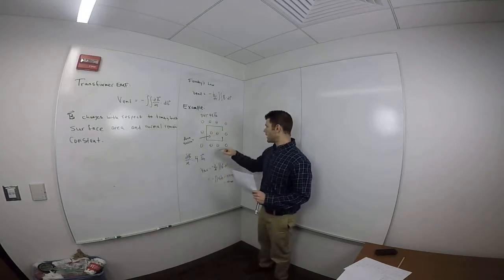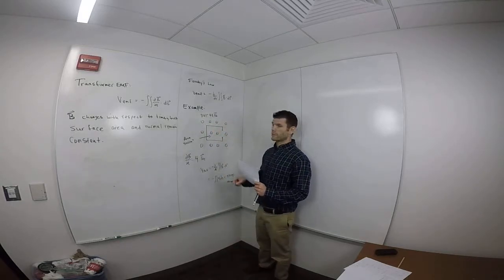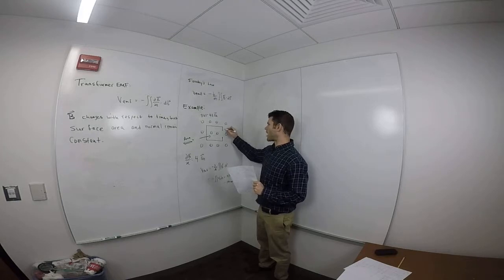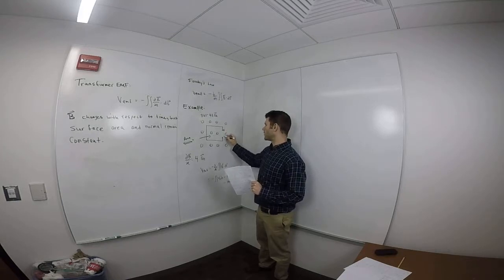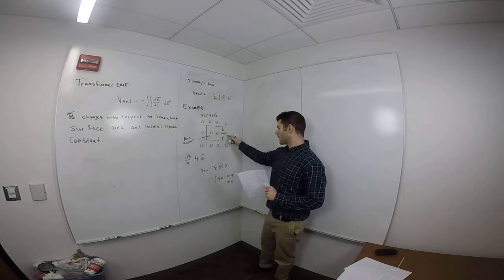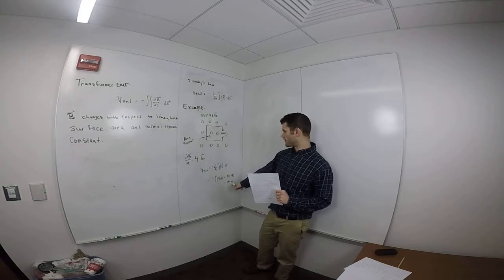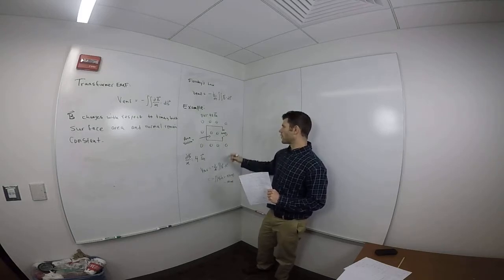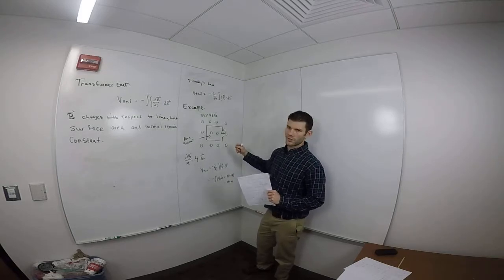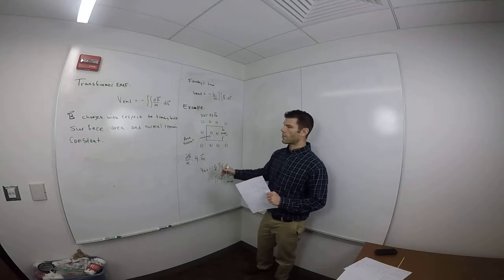If we have an induced current which is clockwise, that means we have to have a higher potential here than we do here. So the induced voltage would be 160 millivolts here. Again, I don't want you to get confused with the negative sign. You just have to ask what the positive polarity would be to produce a current such that it obeys Lenz's law.